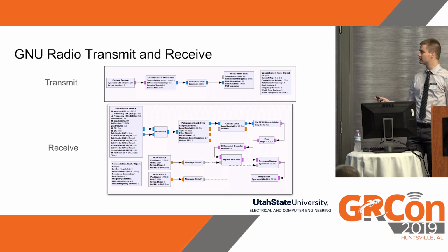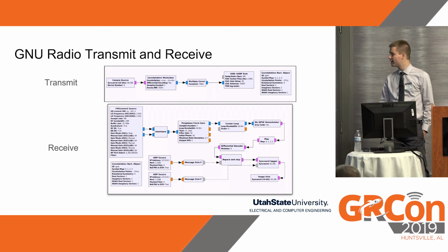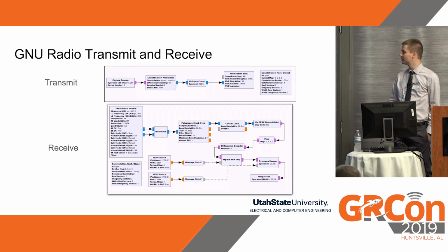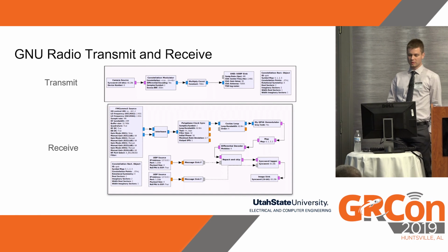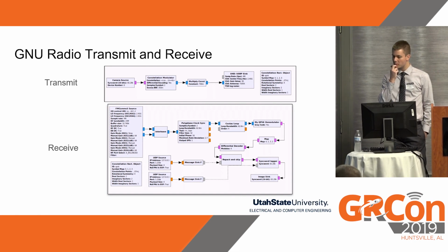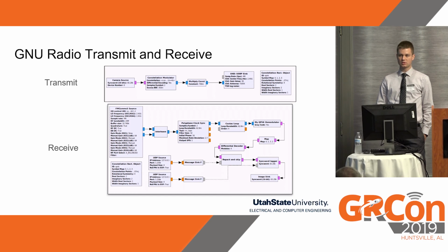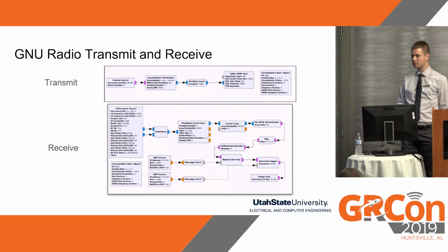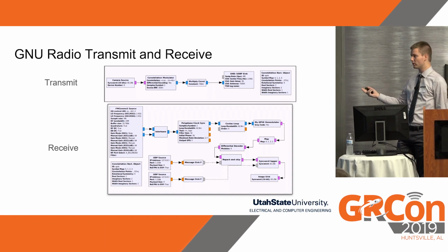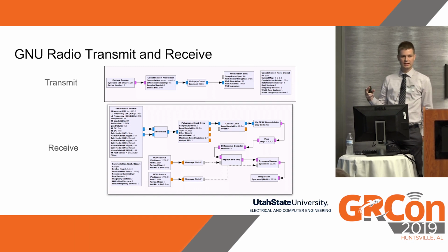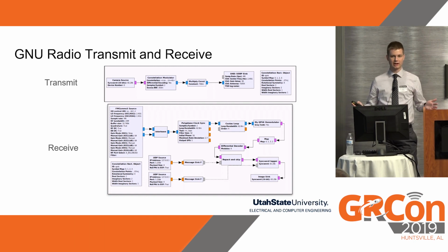So the first thing we do is de-interleave those, send them through some clock synchronization, timing recovery, etc., demodulate, and pull the frames out and display them. So fairly simple. And in this, GNU Radio proved to be a really useful tool. We were pretty constrained on time and budget for this proof of concept. And so having the availability of GNU Radio to just drag and drop receive blocks and not having to build up an entire receiver architecture just for this proof of concept was really valuable for us.